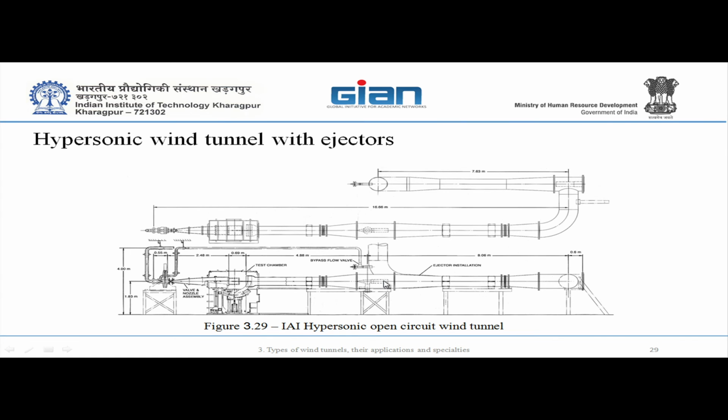For the ejector to run, it requires an air supply. This is a different supply, the supply of the ejector. The supply for the ejector is coming from the storage tanks of the supersonic tower. It is cold air only. You prefer it cold. Is it a two-stage ejector system or only single stage? Two stages. One is this one, and another one is here, the second ejector.